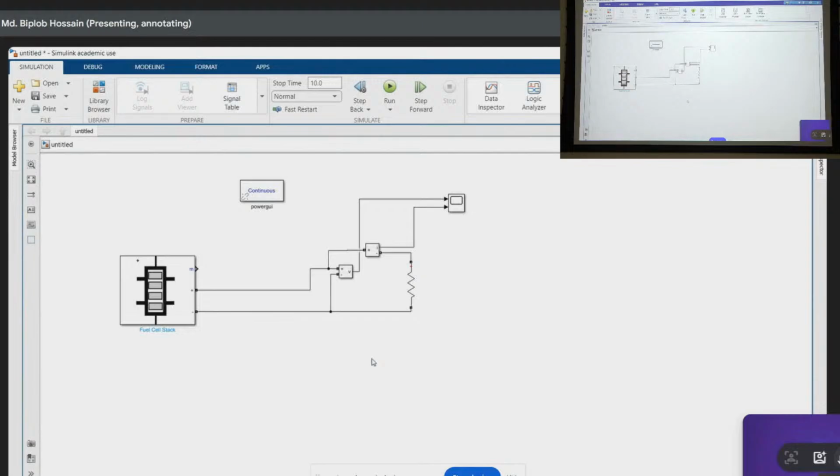And if you have only a mathematical model, that means you don't have any components like an IGBT, a diode, or a transistor, then you can go only for phasor mode. Phasor mode is a little bit quicker. Actually, this provides you RMS analysis. Yeah.